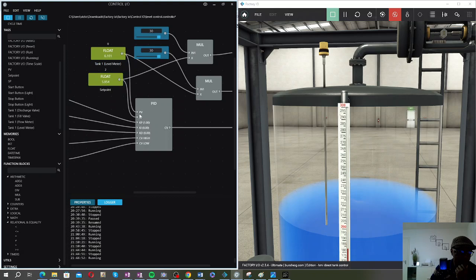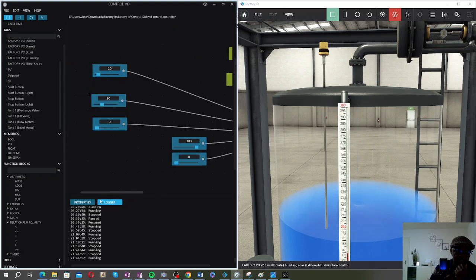You have the process value, the set points, and the gains: the proportional gain, the integral gain, the derivative gain, and your high and low values, the maximum values that you can have in the system. Now, what control engineers do is look for the values, how you can find the values for these controllers. If you can do this, you are a big boy. You'll be sought after, because to design a PID control system, you must know the system.